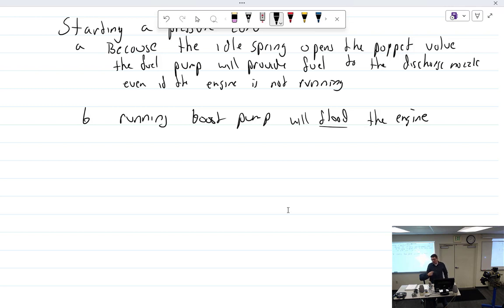It's below even idle. With the throttle plate all the way open, there's not enough air going through the venturi to draw any fuel out. You've opened the throttle plate, so there's no suction on the idle jet, so you're getting no fuel whatsoever. Then you'll get that air coming through, which will start washing some of the fuel out. It'll usually start at that point, and then bring the throttle back.